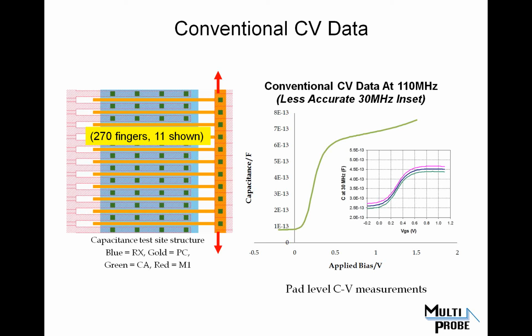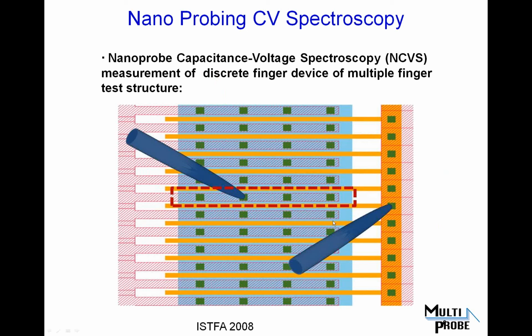Those devices are typically the parametric characterization test structures. So those are the process monitors that are done. Well, we happened to pull one, or Terry did. IBM was nice enough to pull that out so that they could calibrate it, and he had the measurement. So we know what the capacitance is of that entire test structure. And then what they did was strip off the metal layers and measure the structure at contact, and what you end up with is this thing being divided up into individual fingers, or say half a finger on one side and half a finger on another.